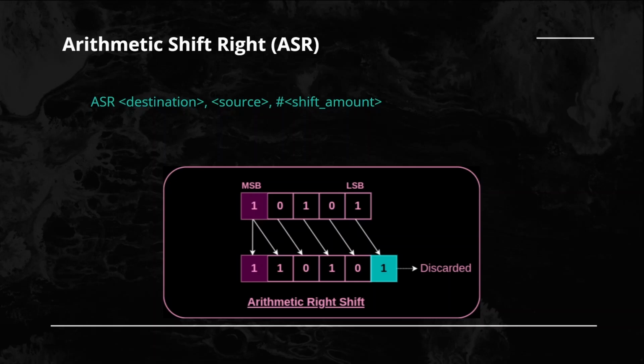So what do you understand by this? As you know, the negative of any value in ARM assembly is its 2's complement, and if you get the 2's complement of a positive number, the most significant bit will be 1, and the most significant bit of the positive number will be 0.